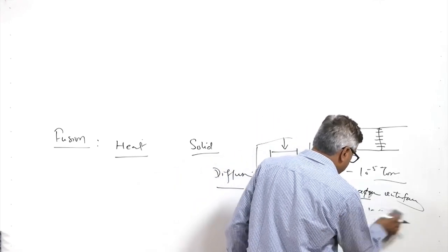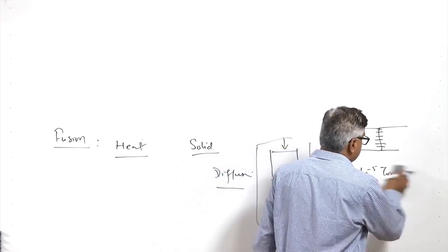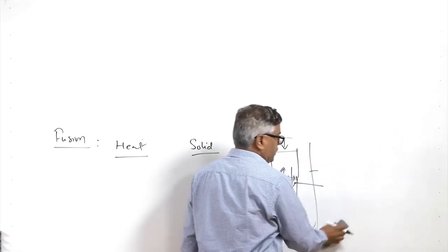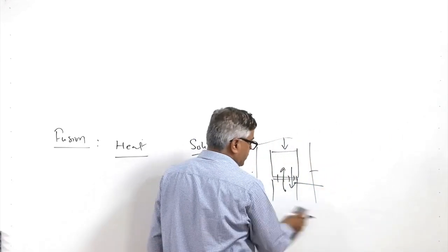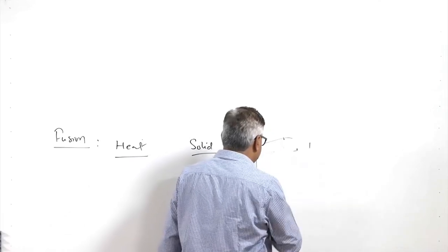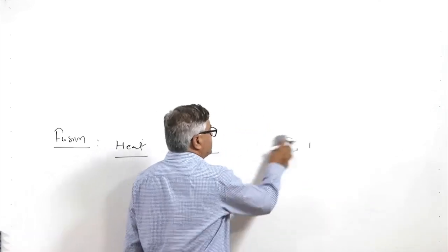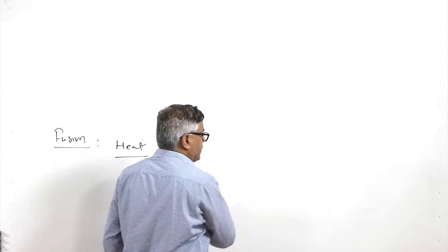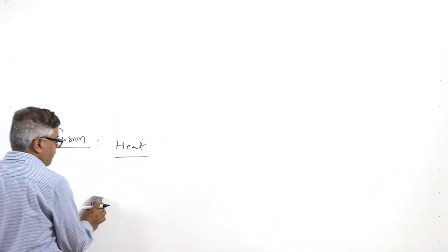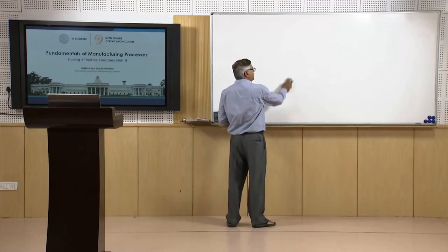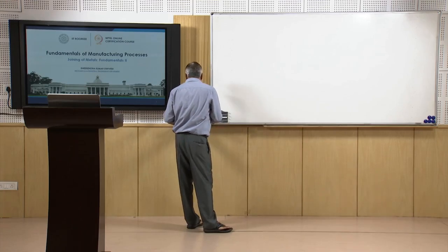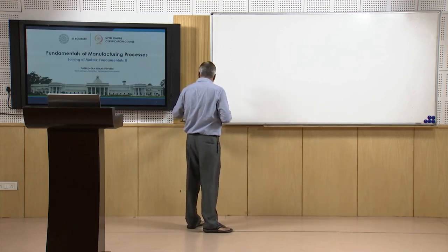Various approaches are being tried in order to increase the effectiveness of the diffusion bonding process through the pressure pulsation or by putting in a soft material interlayer, so that the diffusion and the metallurgical connectivity, meaning the metal to metal contact, can be enhanced through the use of the pressure pulsation, increasing the pressure, as well as the use of a soft metal interlayer like copper, nickel, or silver, which are the common metal systems used for this purpose.